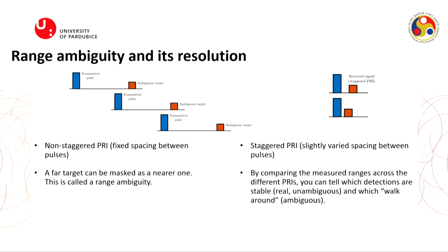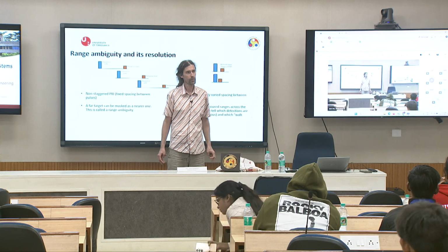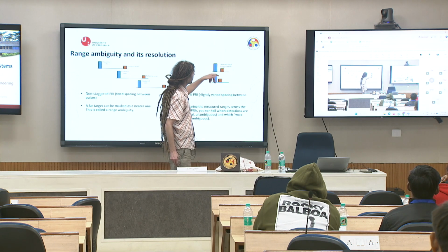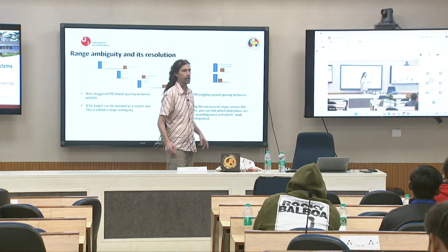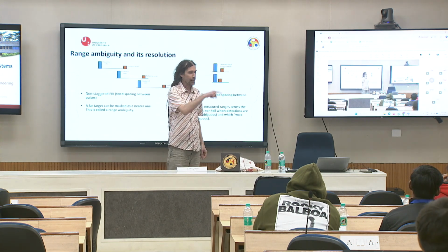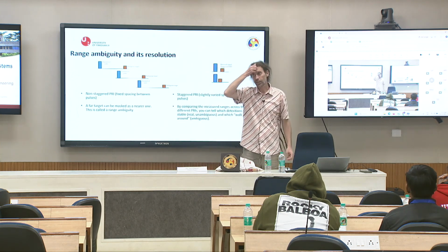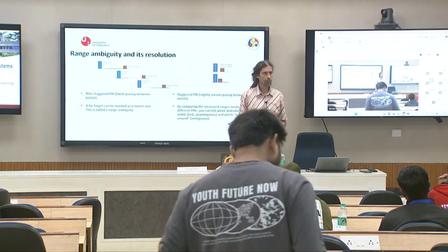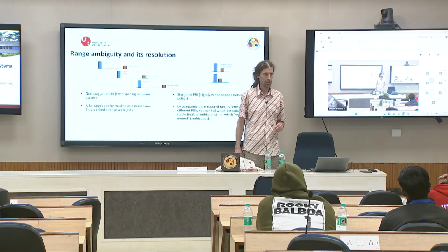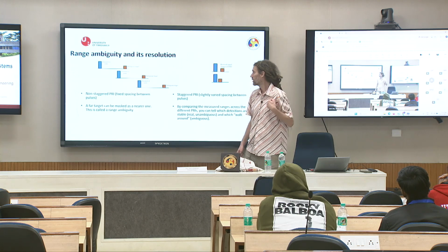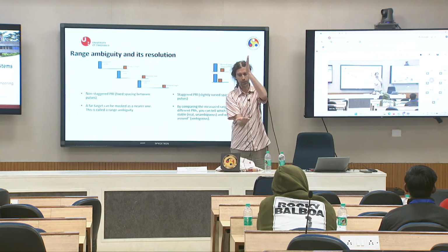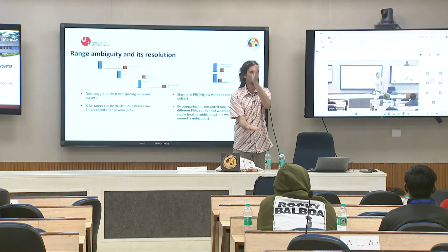We receive the number of samples, and we compare both, and after that you compare both results from the time delay. In my example you will see that you have one ambiguity: the real target will be at 210 kilometers, but my detection will be at 60 kilometers, and always you will receive 60, 60, 60. But it is a wrong value.